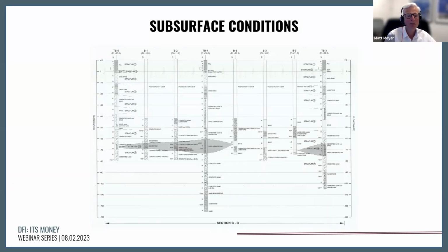And from about elevation -10 to the termination depth of the borings at about elevation -125, which is about 135 feet below grade, we're in and out of various degrees of cementation, but a sedimentary geologic limestone, calcareous sandstone, coconut limestone profile with interbedded, intermixed zones of granular materials with varying degrees of cementation. So a very complex subsurface profile relative to SPT N values, consistencies, and hardness.